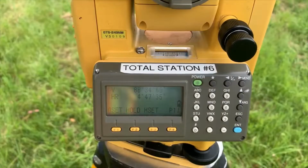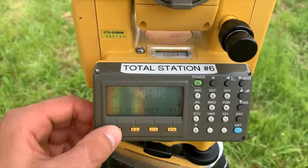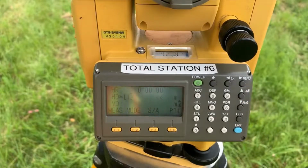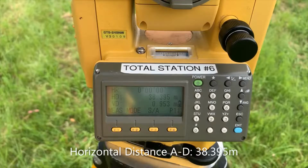So now our total station is set up over point A6 and sighted on a prism over D6. So we'll go to our angle mode and zero set our horizontal rotation, and then go back to our distance mode and take a horizontal distance reading, which is 38.395 meters.